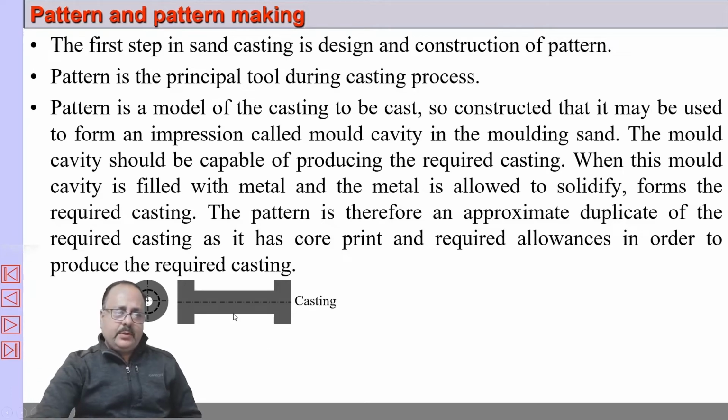Suppose in this example, this is the dumbbell shape, having an internal hole. Now this hole has to be produced, and for producing this hole we require to use a core. Now for inserting the core in the mold, we require core print.